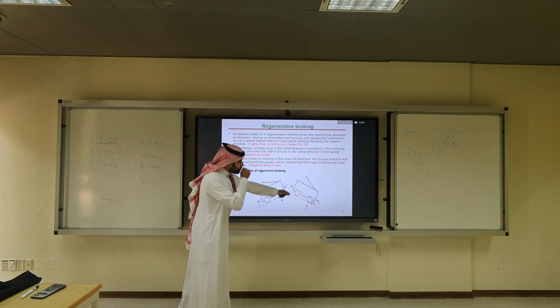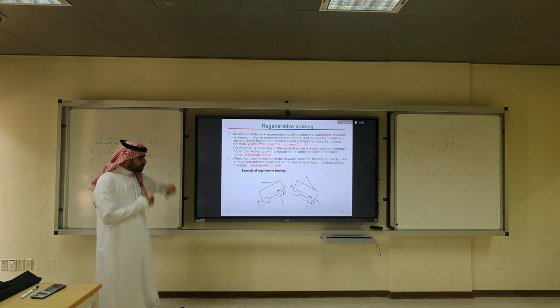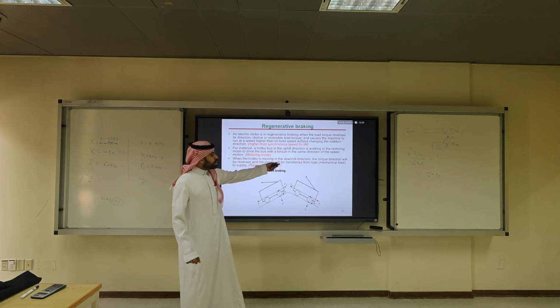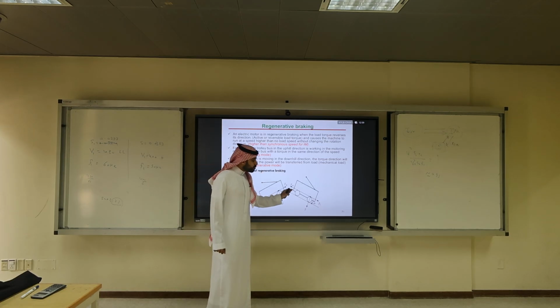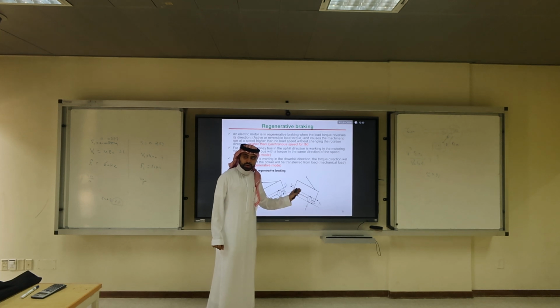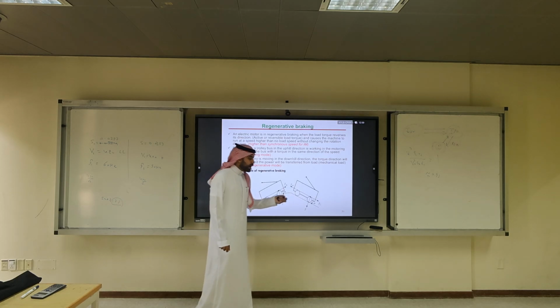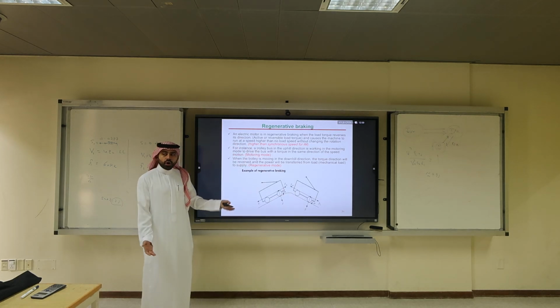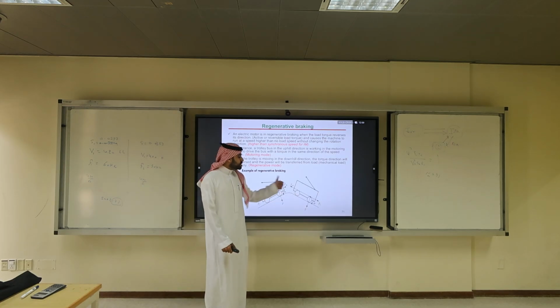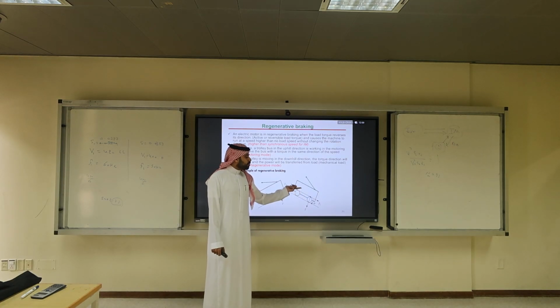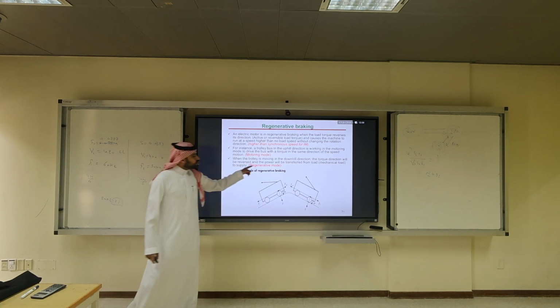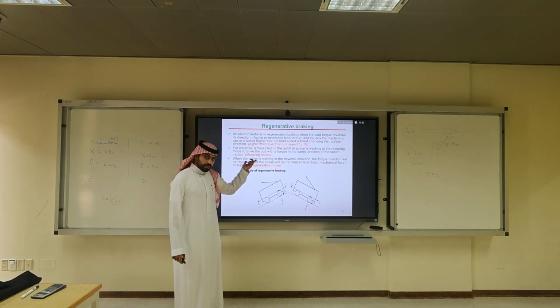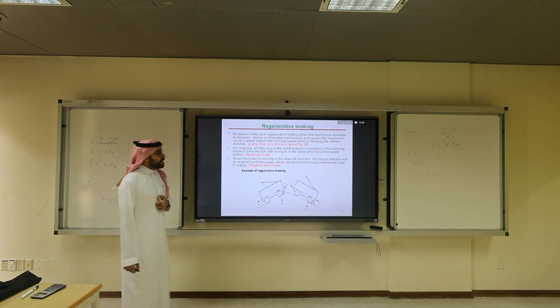Now when you go downhill, what will happen? When the trolley is moving downhill, the torque direction will be reversed and the power will be transferred from the load. Now, will I apply a torque by the machine or will the load apply torque in the machine at this time? The load. The load will apply. The controller, there is no point of putting a torque, that's opposite. So now we are in the generator mode, okay? So now we are in the regenerative mode. It's a generation, but it's called regenerative braking, okay?